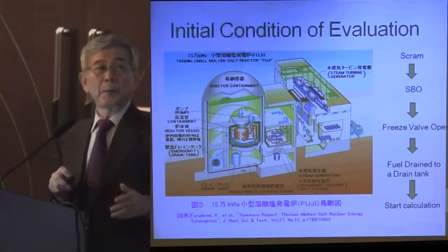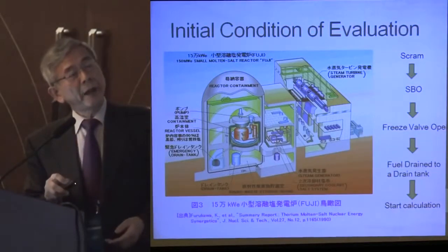But in an actual plant, we would have to analyze the transient: how long would the fuel salt take to be completely drained into the drain tank, and during that period, the coolant temperature, fuel temperature or cooling tube temperature may change.